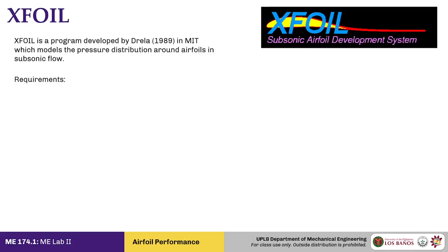Now, what do you need to feed to this Xfoil program? You basically need to feed it fluid flow characteristics and some information on the airfoil. For fluid flow characteristics, you need to feed it the density, the viscosity of the fluid, and of course the Reynolds number, the flow regime of your flow. So if you want to simulate your airflow at varying flow regimes or at varying altitudes in the atmosphere, you have to run a different test essentially.